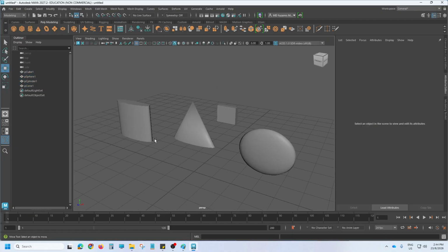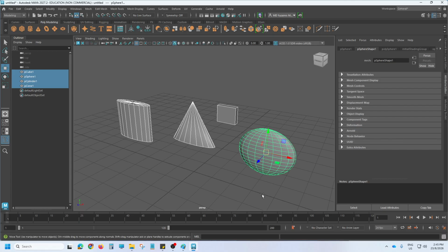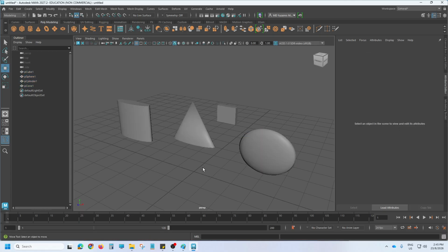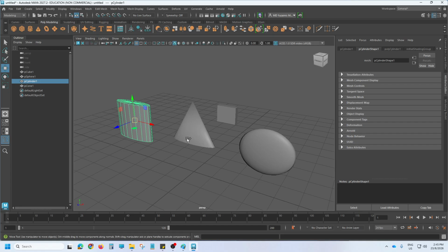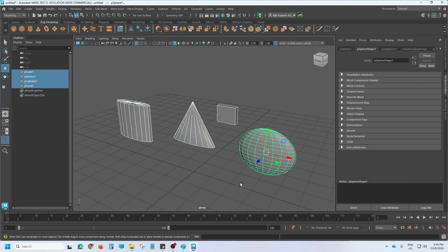Selection, if you want to select multiple objects, of course you can do the rectangular selection, but you can also hold Control plus Shift, and then you can click. See the plus sign on the mouse there? It shows that I can add selection. But if I want to minus selection, I can hold just Control and then unselect the selected one.